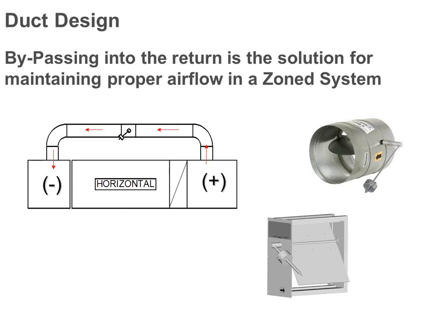However, if I was redoing the ductwork from scratch, what I would want to do is have all my basement ductwork fed off of one trunk run. So instead of having one big trunk that goes down the middle of my house and I tap a bunch of dampers and registers off of it, I would want one trunk run that goes to the basement and all my basement splices come off of there. Then I'd have a separate trunk run that would go to the upstairs and then a separate one for the second floor. I'd want to have the ductwork lined up that way from the get-go instead of just randomly having it taken off the nearest point.